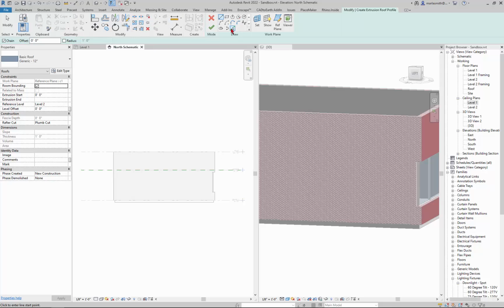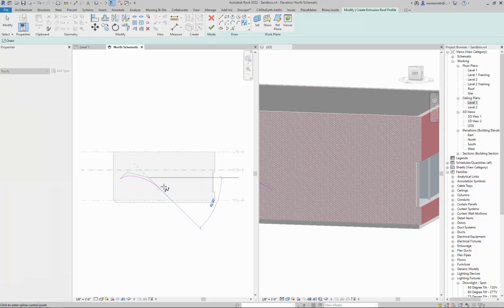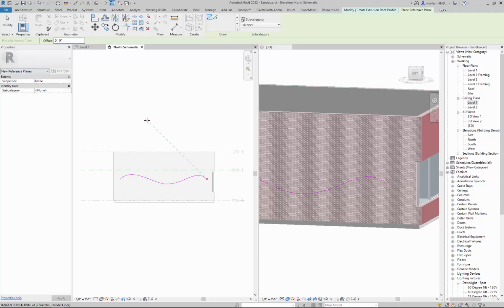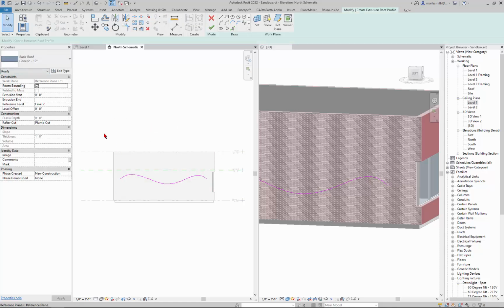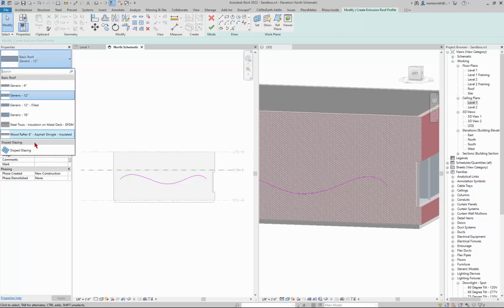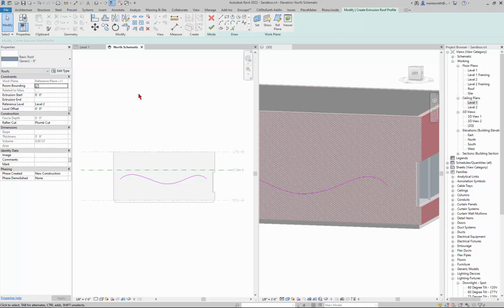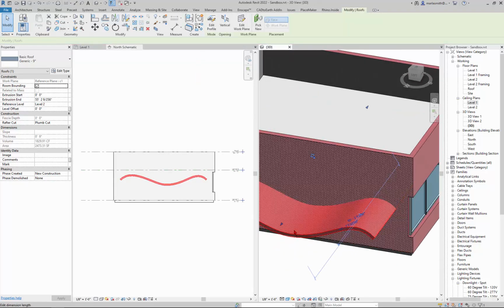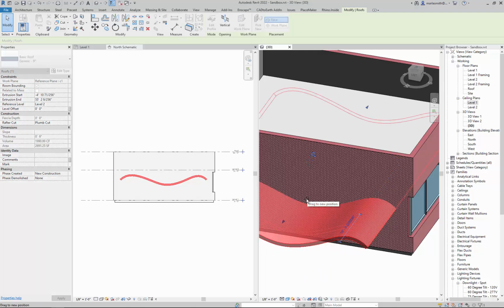And then it goes into sketch mode, and if I wanted to make a ceiling that was maybe doing something a little bit more swoopy but still in a constant section, I can make a line like that, and let me hit escape a couple of times, and it will put a roof on it. So any roof that I pick, it will put on it. So if I go generic 9-inch and I hit check, I now get this extruded, and I get little pull options, right, where I can pull it bigger or smaller.